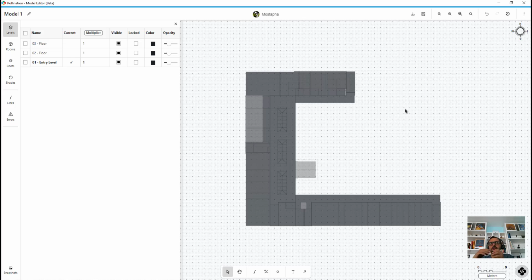One thing to keep in mind, I don't know if I already said it, is that you don't want to clean up the model too much. Depending on the software that you're using, if this is not a problem, then you don't spend time to clean things up. In some cases, for example if you export to EnergyPlus or OpenStudio and you have edges that are very tiny, they will be aligned depending on the tolerance, and we clean them up in the process. But again, if you have a clean model, then of course you're going to save a lot of time when you run simulation because you are not going to get random errors, and also the model is reliable.